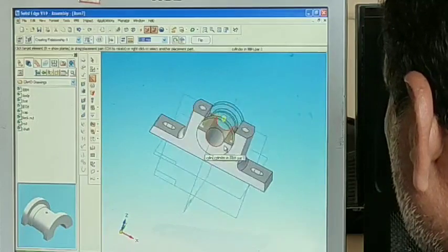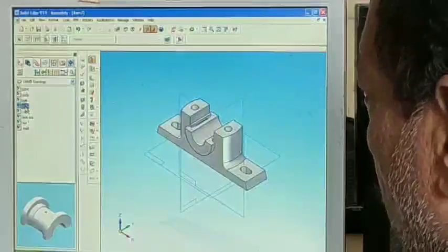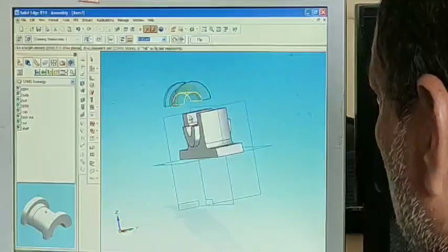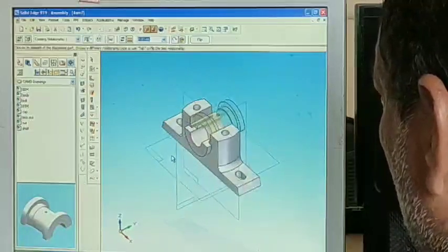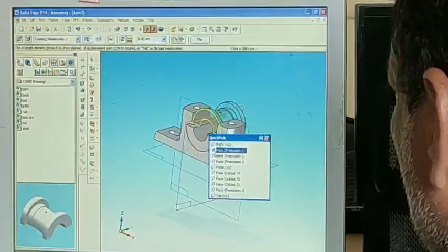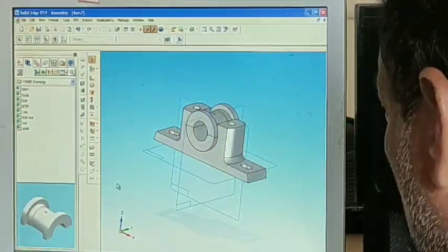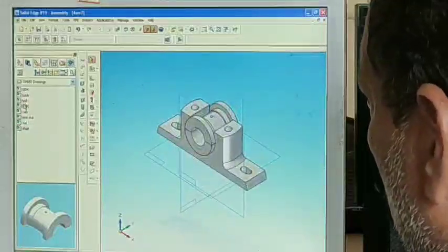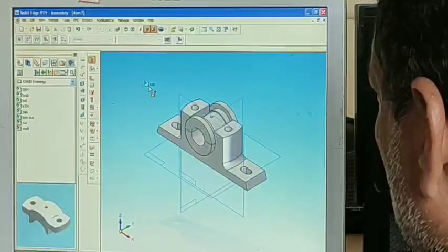I am again going for bearing top half. Drag this one here. So go to axial rotation lock with this axial. Now planar with this face. So now this has been fitted. Control F. Observe here. So now go to cap. Drag it here.